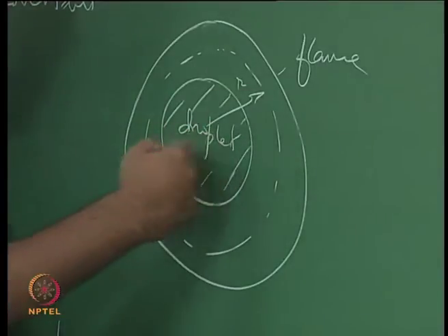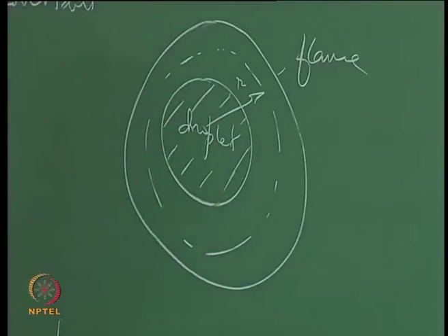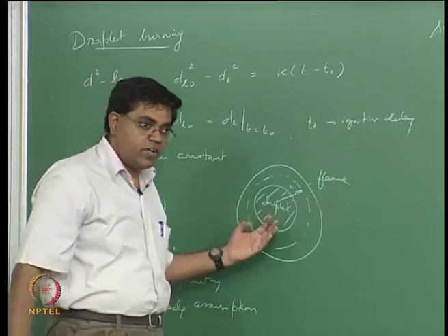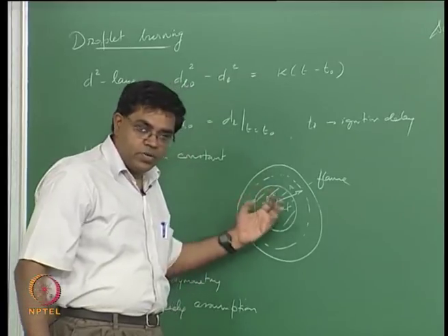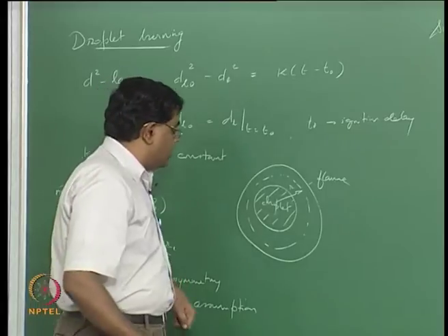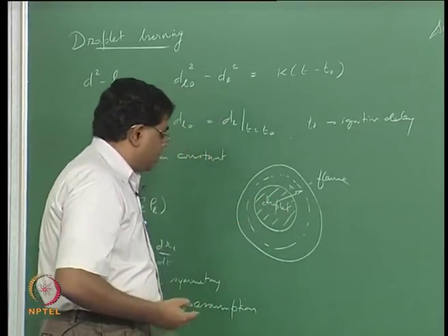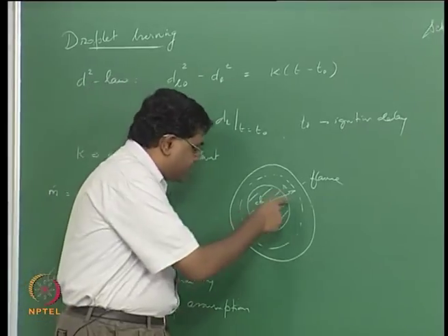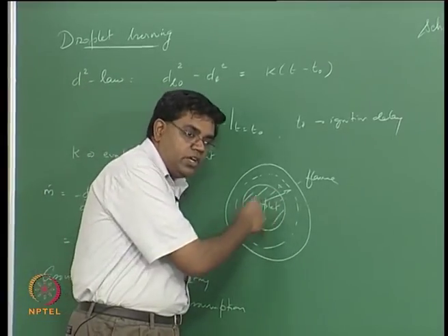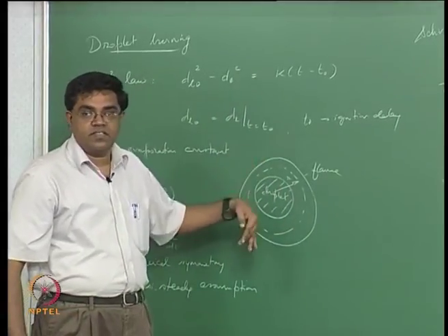And then of course inside the droplet you could have a constant temperature if the droplet is small, so thermal equilibrium must happen significantly, considering that liquid thermal conductivities are an order more than the gaseous thermal conductivity and so on. Or let's say you still have a profile that's going in, but at the temperatures of the boiling point of the liquid, the product could also condense into a liquid, okay.